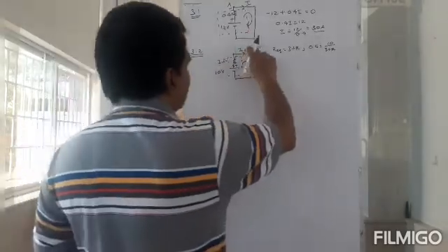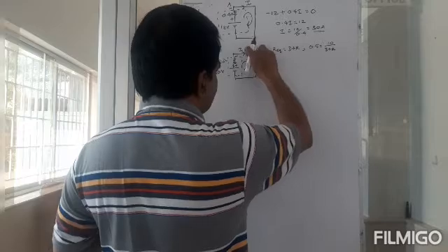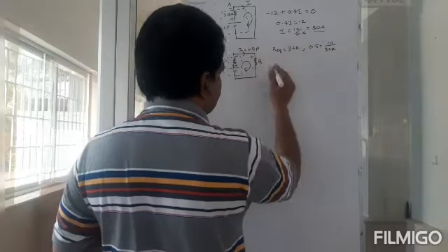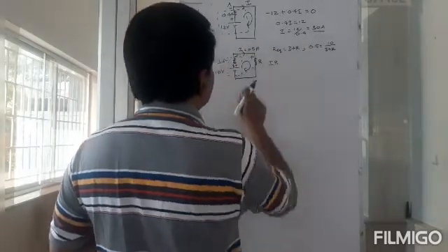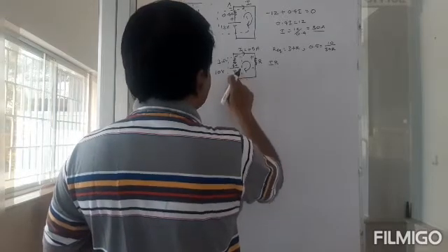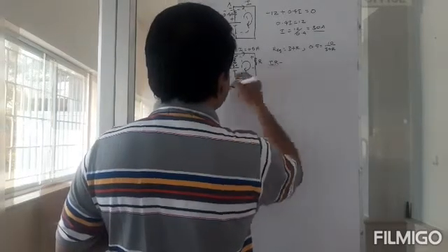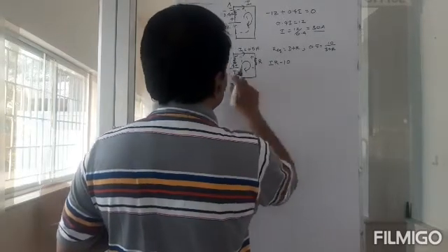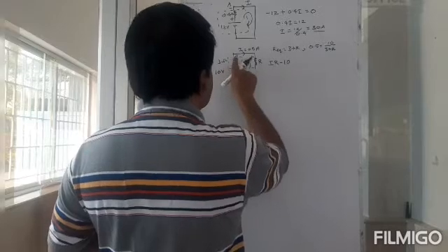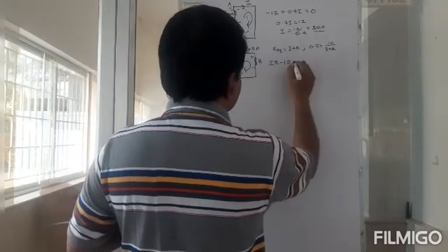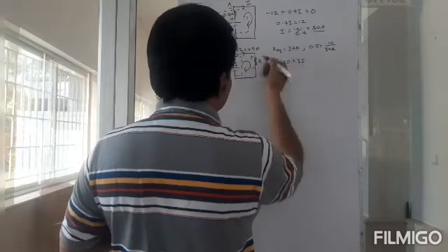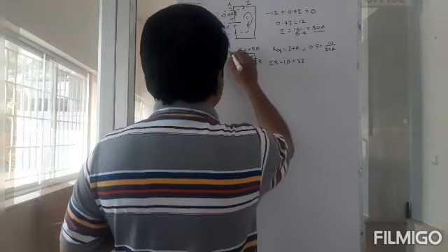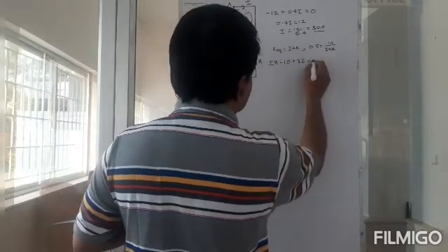Okay, so now this is going to be IR, that's the voltage drop. I am entering the resistance at the positive end, so IR. Okay, and I come here, I enter the battery through the negative terminal, so that is 10. And then I enter this resistance at the positive end, so that's going to be 3 into I. Okay, I is 0.5 and load again. So that is A. I'll come back to A, which is equal to 0.